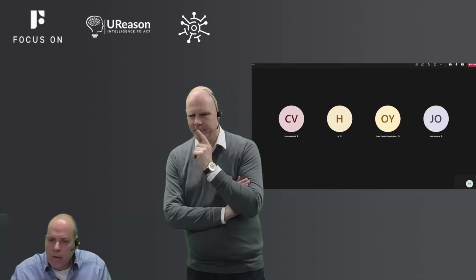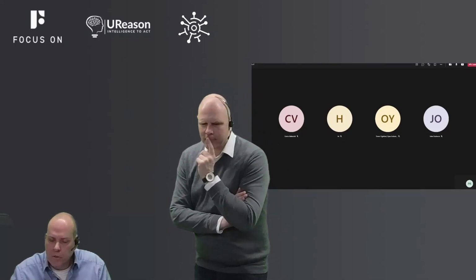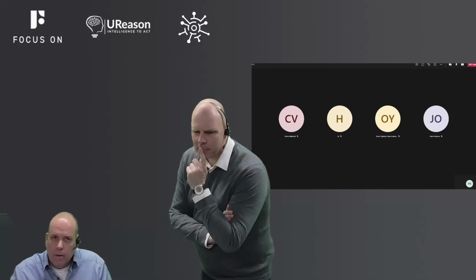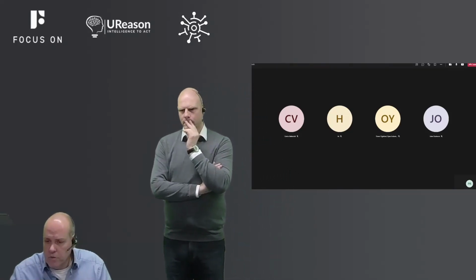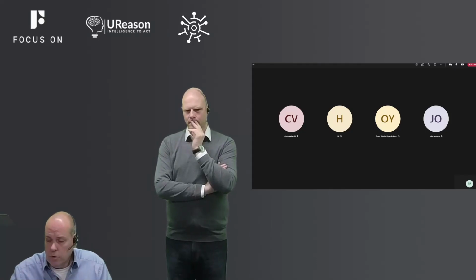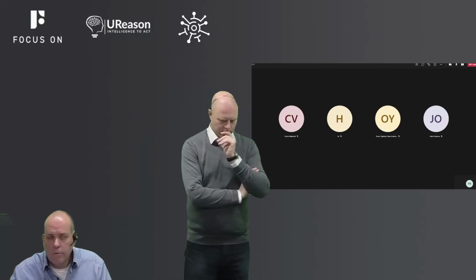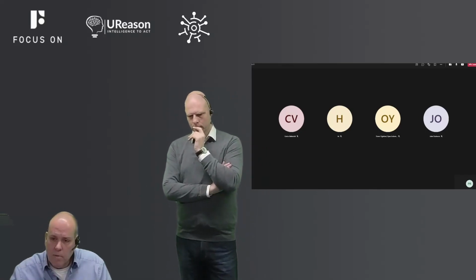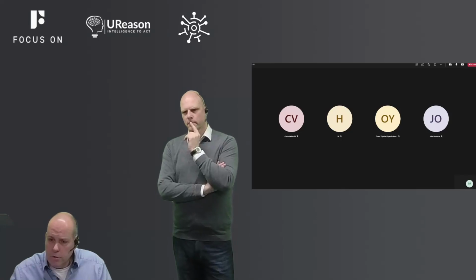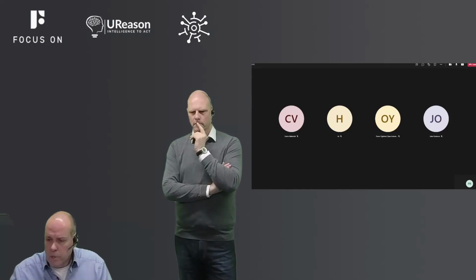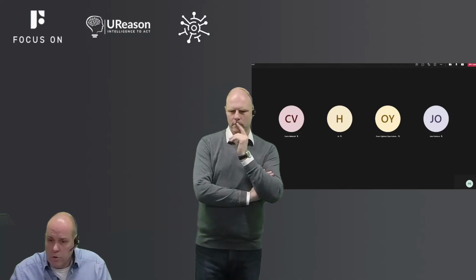There's a question by Jos. In the reference architecture, there's mention of MQTT. What about OPC UA? A very valid question, Jos. In the OEC publication of the Open Industry 4.0 Alliance, MQTT is used as a transport between the field and edge devices. If you go towards secure communications, if you need to do a protocol switch, OPC UA is also supported. But it's also notably true that the message content, the payload that we embed in the OI4 OEC data that is published, is OPC UA Part 100 compliant. So OPC UA is also used in the demonstration architecture that I showed earlier on. You saw that OPC UA is actually one of the data providers in the total reference architecture. So we also support this.